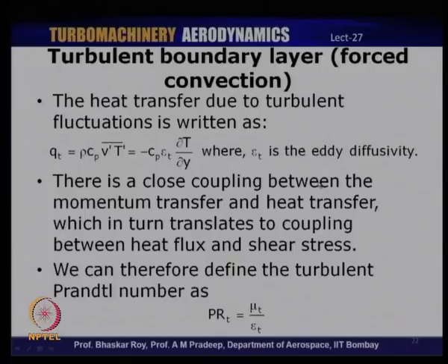In a turbulent flow, there is also a very close coupling between the momentum transfer and heat transfer, which in turn translates to the coupling between the heat flux and shear stress. Because in a turbulent boundary layer, we know that there is momentum exchange between the different layers of the flow, which is absent in the case of a laminar boundary layer, and therefore, there is a close coupling between the momentum transfer and heat transfer.